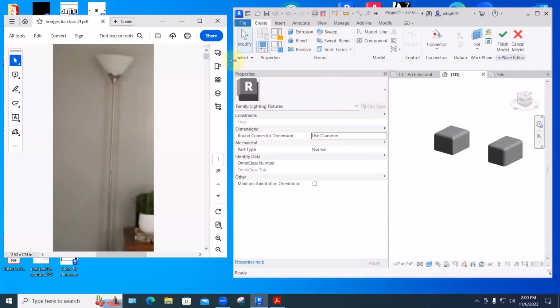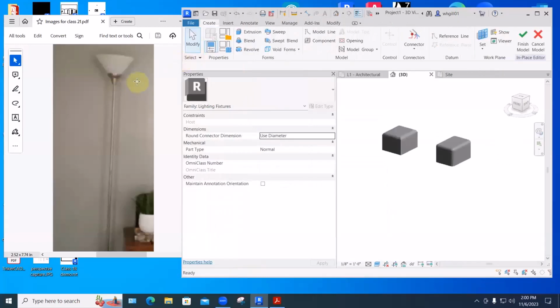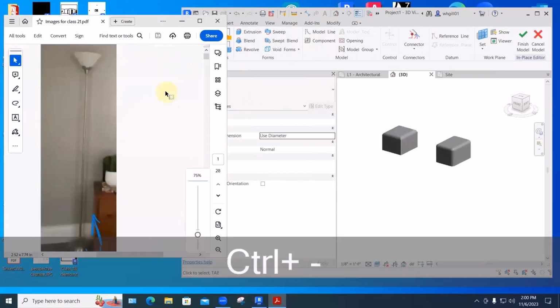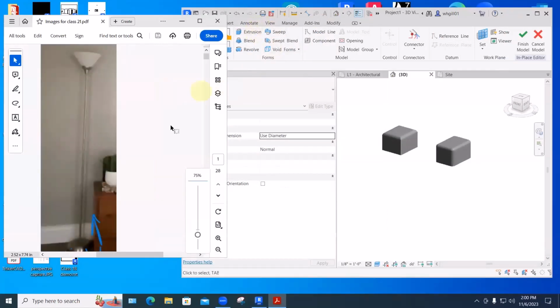Which of these tools are going to be useful to us in making the shapes here? What are our options? We got extrusions. You can certainly see this becoming an extrusion all the way straight up. How about the base, rounded all the way around? I would say revolve for that. Let's just write revolve next to each one. And you could say extrusion for the top one. How else could the cylinder be modeled? What I'm working towards is what's the easiest darn way to make this fixture?